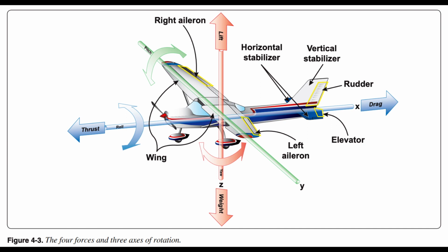This force acts straight up from the average, called mean, center of pressure, CP, which is called the center of lift. It should be noted that it is a point along the chord line of an airfoil through which all aerodynamic forces are considered to act. The magnitude of lift varies proportionally with speed, air density, shape and size of the airfoil, and AOA. During straight and level flight, lift and weight are equal. End of page 4-2.